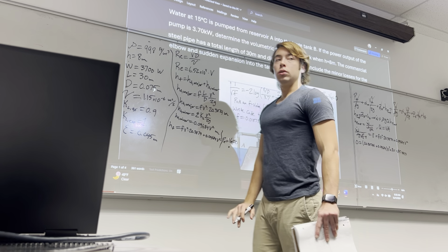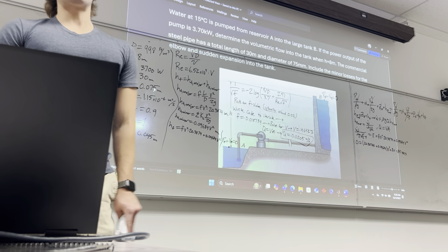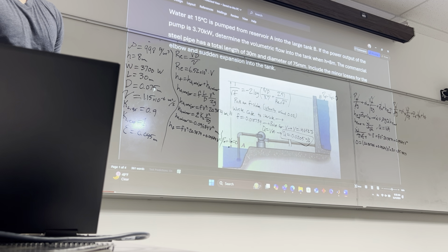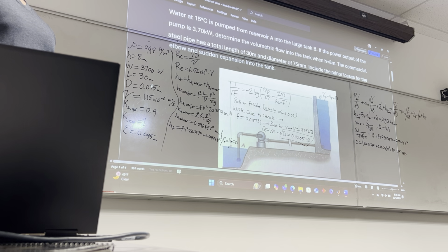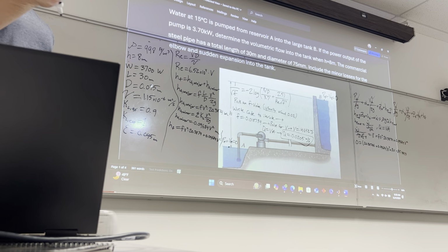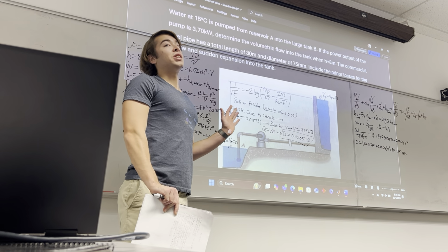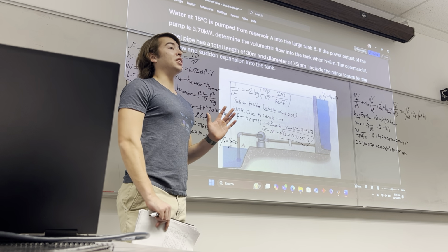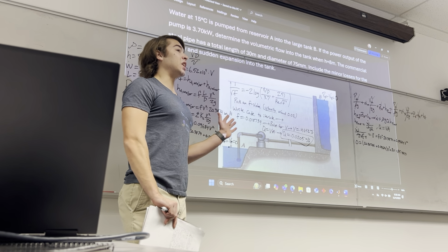You can see how on an exam that would be pretty brutal, having to sit there and iterate for hours and hours over 2 different values, having to find one to guess another one and repeat the whole process over again. That would take a while. On an exam, if you are going to have to iterate, you'll know a Reynolds number, you'll know a velocity, it'll be a lot smoother. But yeah, if you pick 0.02 as your starting point, you can usually get this whole thing to converge in like 4 steps tops. If it's a really bad situation, it's not gonna be that bad.